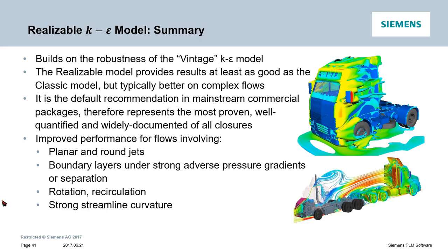And performance is substantially improved for non-equilibrium scenarios like planar and round jets. So it addresses the round jet anomaly, boundary layers under strong adverse pressure gradients and separation, and other non-equilibrium flows like rotation, recirculation, and streamline curvature.